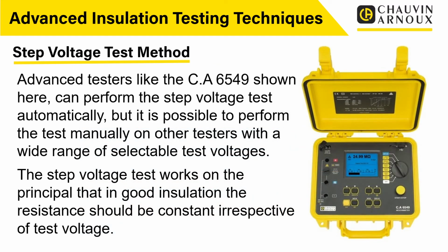Now, the next test we're going to look at is slightly different. This is the step voltage test method. Advanced testers like the CA6549 shown here can perform the step voltage test automatically, but it is possible to perform this test manually on other testers with a wide range of selectable test voltages.